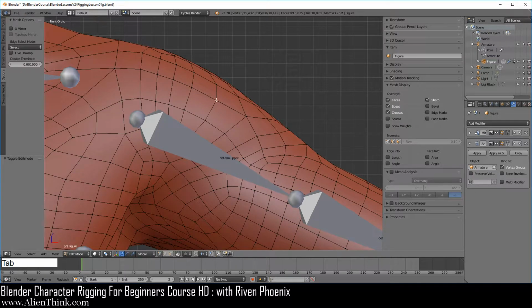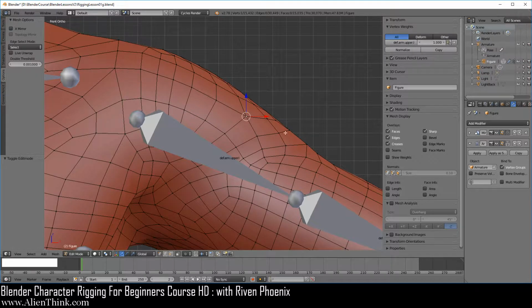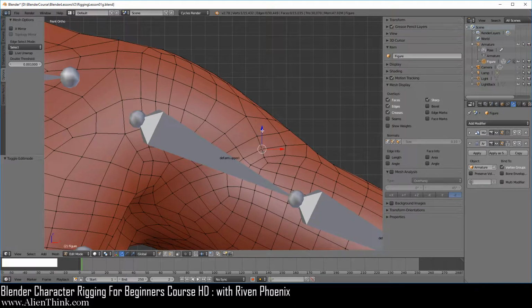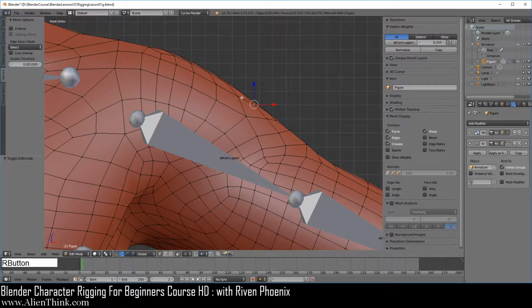Now when we press the tab key, you're going to see these additional faces. Remember, we applied the vertex group over here. Because of the subdivision modifier, when the faces are getting generated mathematically, Blender is going to automatically assign this same vertex group to the surrounding vertices. So if you click over here, notice that the value is now starting to go down, right? And over here, it's not going to appear. So it will basically assign the vertex group to the surrounding vertices, and this is the one we started out with, and notice that the value is just different. Okay, so just keep that in mind.